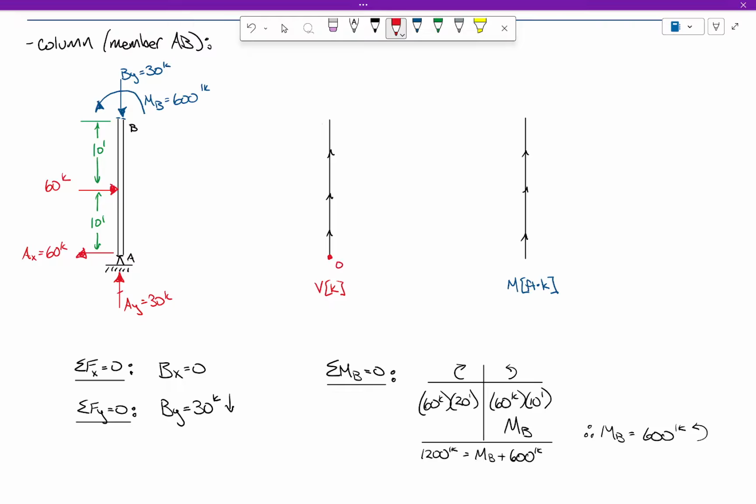Okay? So, how does a shear diagram work? We start at 0 and we should be ending at 0. So, I want you to think of it kind of like this. Think about it like we've rotated the coordinate system. This is our x-axis and our y-axis is like that. So, this is x and this is y, so this is me just turning it, okay? So that means that positive shears would go this way, negative shears would go that way. Does that make sense?